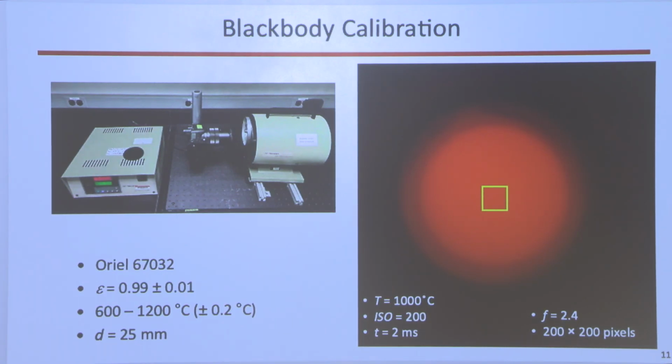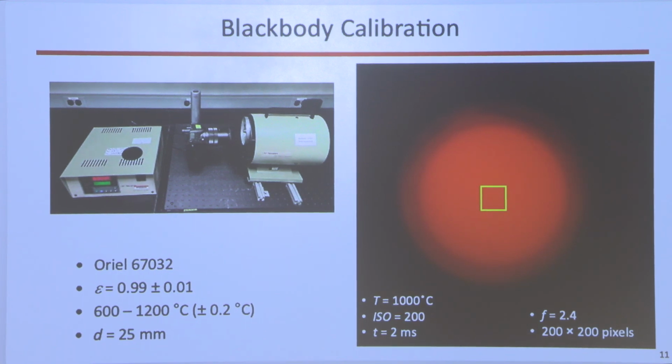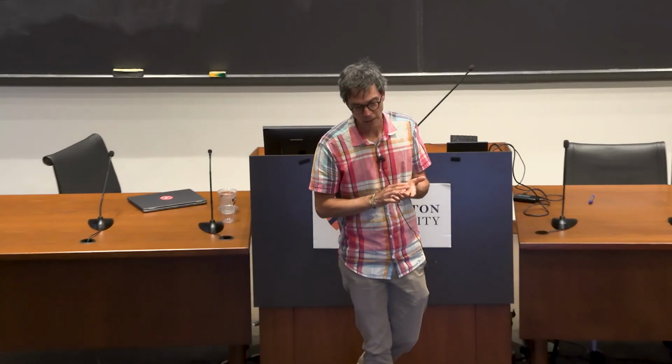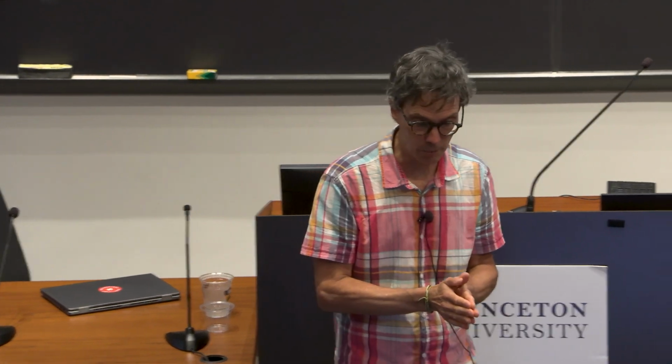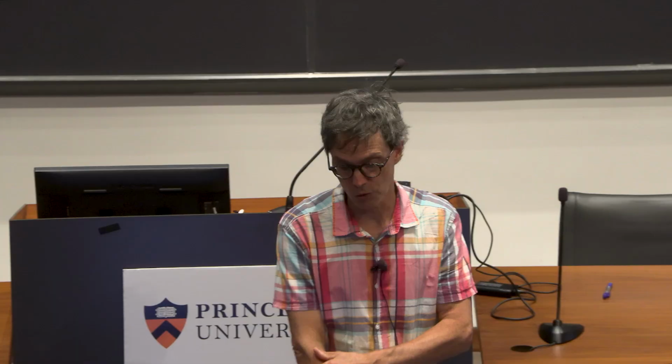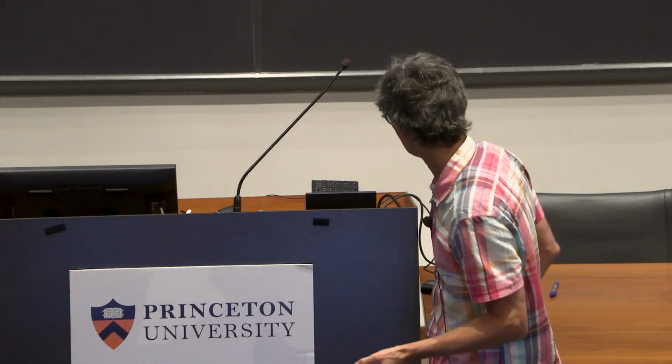And that's how the black body works. It looks like a nice, inexpensive thing that anybody can buy in your lab for a few $100s, but I think the going price on this now is about $25,000. They're expensive because they're heavy. A lot of metals will melt at 1200 degrees C, and it needs to be isothermal and black on the inside and calibrated and with a nice temperature controller. So it's a very useful device if you're going to do pyrometry, but also an expensive device.